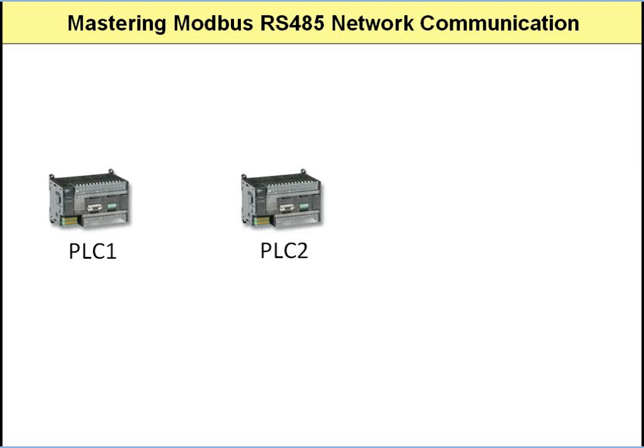Onto PLC1 we have a pressure sensor and a temperature sensor connected. Onto PLC2 we have two discrete inputs connected to two different valves, V1 and V2. These discrete inputs actually read the position of the valve, whether it's open or closed. Now normally these PLCs would simply run as a standalone system, but management has taken a decision that they would like to get pressure, temperature and valve position data transmitted wirelessly back to the marine base.